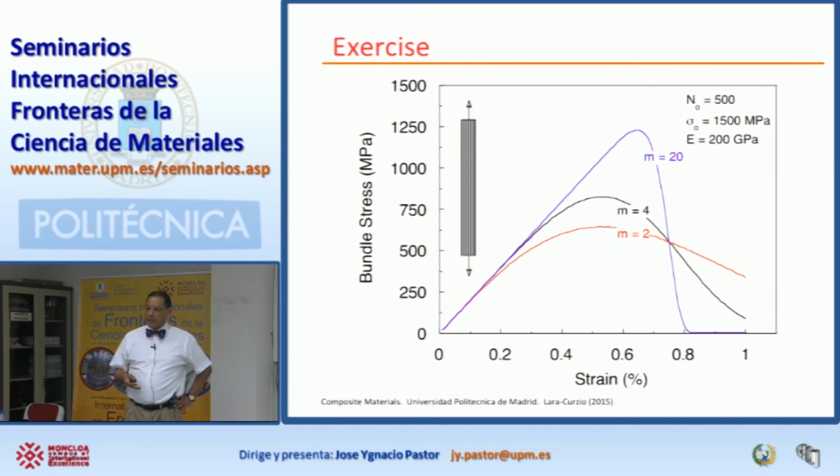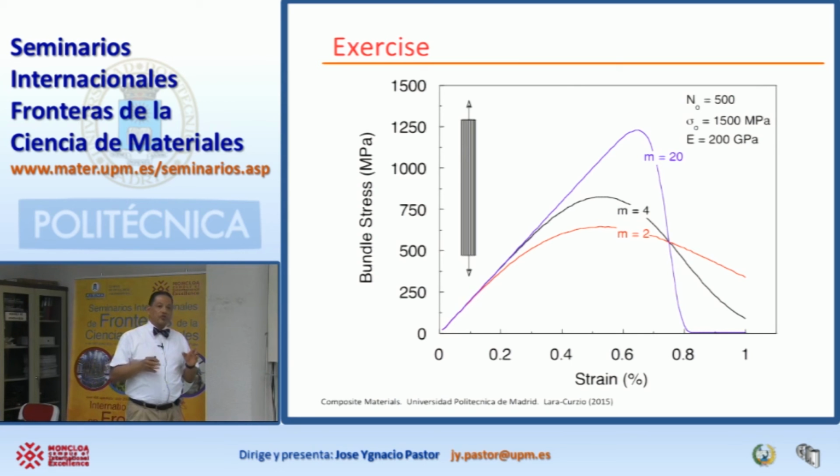The reason why ceramic matrix composite can be tough is because you have a stochastic distribution of strengths in the fibers. Okay? Now, if you glue the fibers to the matrix very strongly, you're going to have this type of behavior. The first time a crack propagates to the matrix, it's going to break every fiber. If you allow the fibers to debond from the matrix whenever a crack approaches, then you're going to have this behavior. The fibers are going to be able to debond and slide frictionally in the matrix and be able to carry load. And they may break, but then the fibers can get reloaded and show this type of behavior. Okay? That's the secret behind ceramic matrix composites.